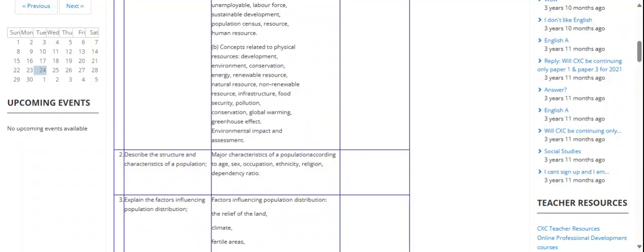So we have sedimentation. In this stage, the water is allowed to settle for a period of time in order to allow all suspended matter to settle. Filtration. The water in this stage is filtered as it passes through a layer of fine sand and a bed of gravel. We have chlorination. This is the final stage where chlorine is added to the water to destroy any bacteria which were not previously removed. That is the full cycle in the stages of water purification.